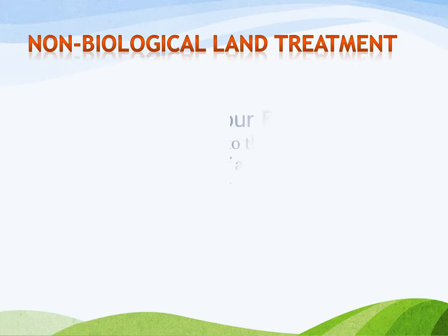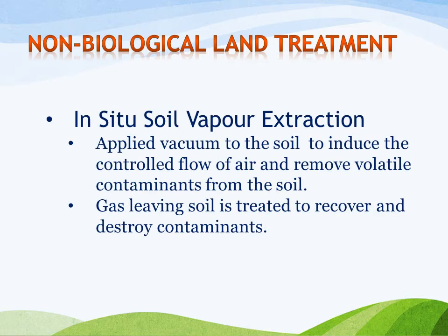Non-biological land treatment. In situ soil vapor extraction applies vacuum to the soil to induce controlled airflow and remove volatile contaminants from the soil. Gas leaving the soil is treated to recover and to destroy contaminants.